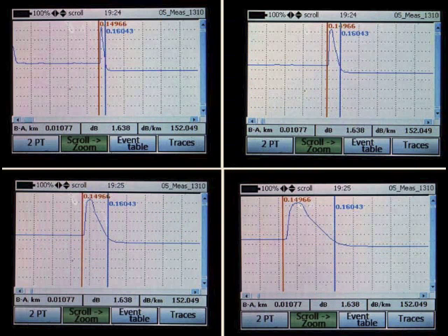Here you can actually see the same trace taken with 4 different pulse widths. On the lower left-hand side was the 25 nanosecond pulse that was chosen by the auto test. On the lower right side is a 100 nanosecond wide pulse, which is appropriate for very long cable plants. There's also a 12 nanosecond pulse in the upper right-hand corner, and the 6 nanosecond pulse in the upper left-hand corner we chose for our test.